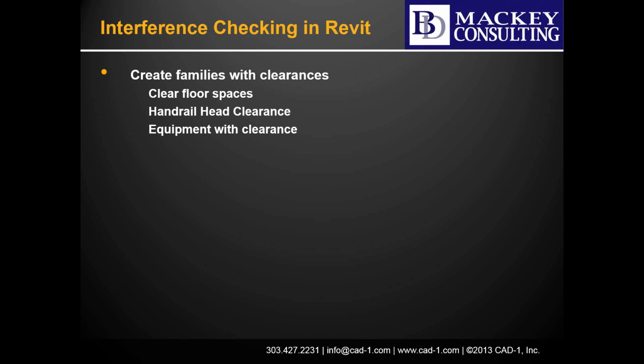So all my little 60-inch round handicap clearance turning circles actually are three-dimensional. So I can go through and say, here, is it going to be clashing with doors? Is it going to be clashing with casework or anything like that? Steve Stafford blogged this a couple years ago, this thought of mine of having handrails that match head clearances. So now I could do handrails to ceilings or handrails to beams to make sure that I'm going to have all the head clearances going in and out of my stairs.